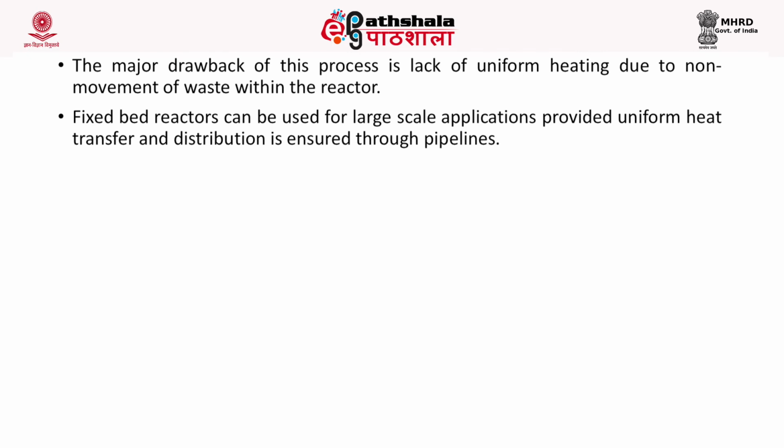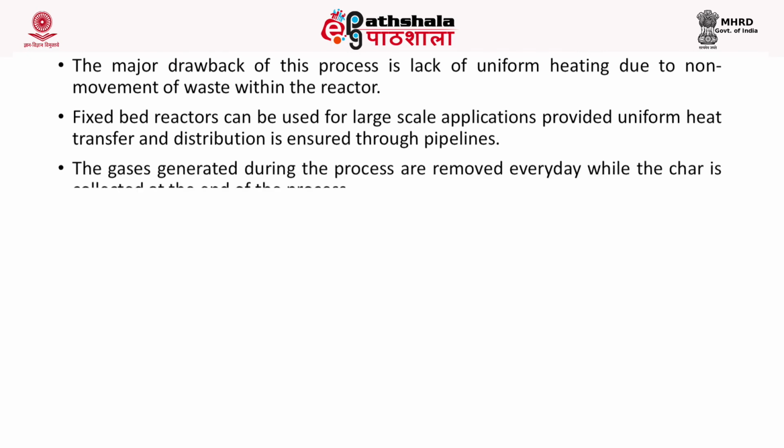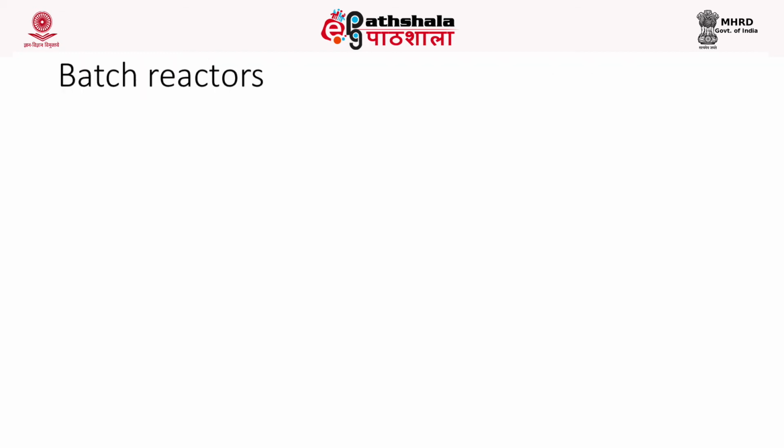The drawback of this particular process is, one, lack of uniform heating due to non-movement of waste within the reactor, and fixed bed reactors can be used for large-scale applications only if the heat transfer and distribution is uniform. The gases generated during the process are removed every day while the char is collected at the end of the process.